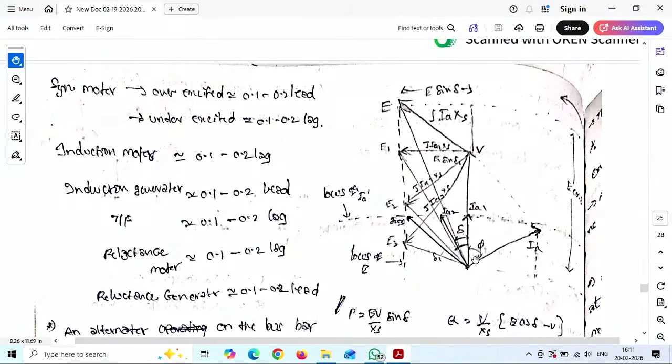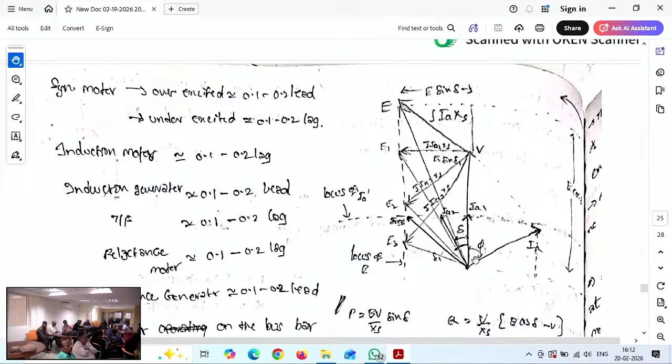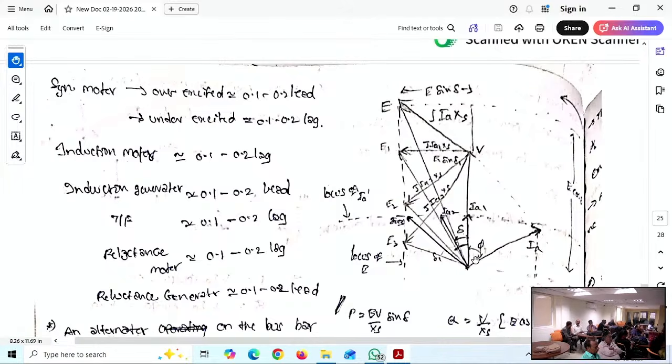Now, if you see this locus of phasors, the resultant plots for each value. Usually you plot one armature current, one plot, IA1 a different plot, IA2, IA3, varying in nature. Slowly I am trying to make you aware of how this varies from lagging power factor to leading power factor. Combining all these plots gives us the locus. From this we can plot a curve called the V or inverted V curves for synchronous machines, provided we understand it for the generator.